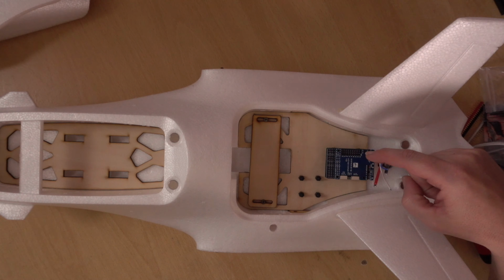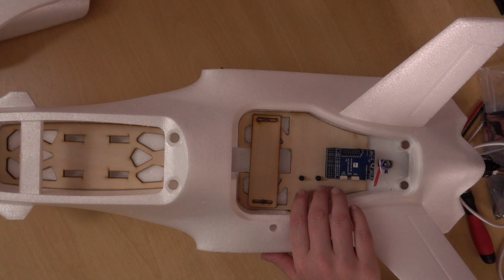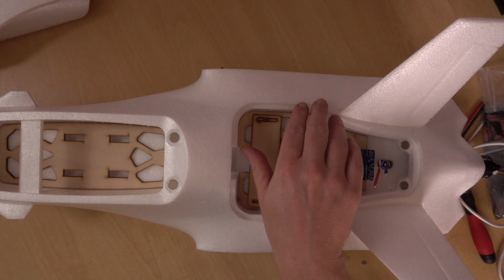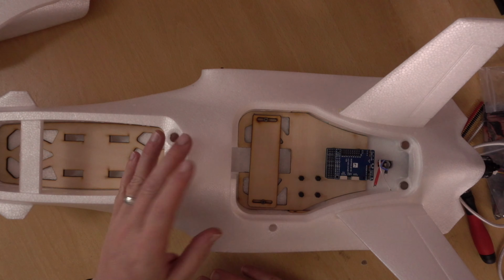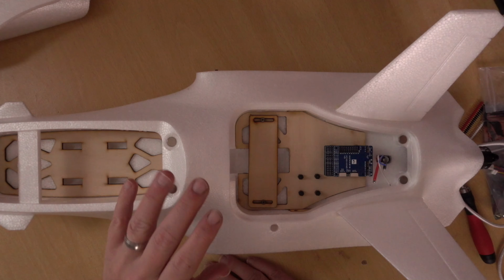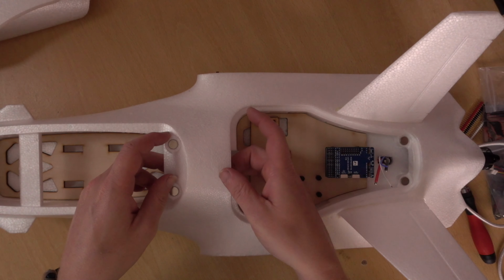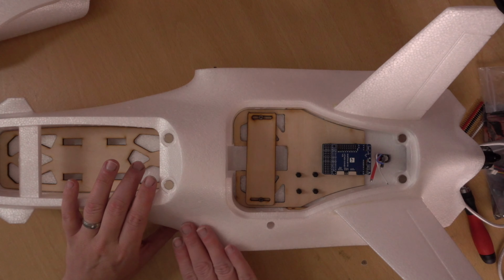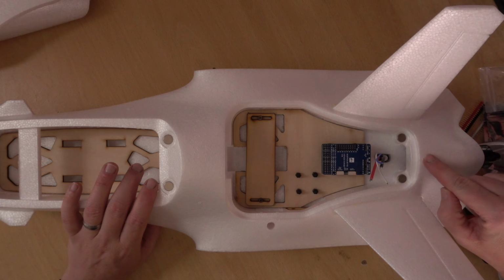We're going to have our flight controller. Because I want to have a build where it's easy for you guys, the VTX will be in here as well, and the receiver. So the VTX I'll put this side so that we can use this nice little section here. The receiver I'll put on the other side. The GPS, I'm actually going to cut the GPS out of the foam just because I think it will be good to demonstrate how we do that. So if you do want to get a bit adventurous, you can get on with that too. So I will find somewhere to put the GPS, so possibly on a shoulder here. Ideally it wants to be somewhere quite flat so that the GPS antenna points straight up. So maybe even here, just above the motor.